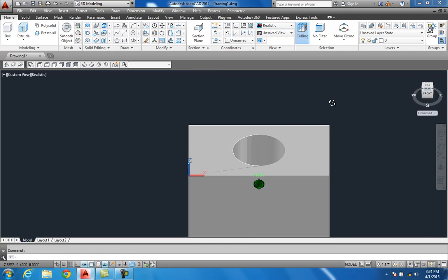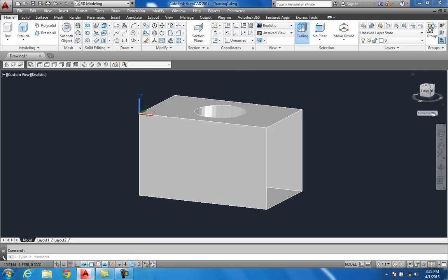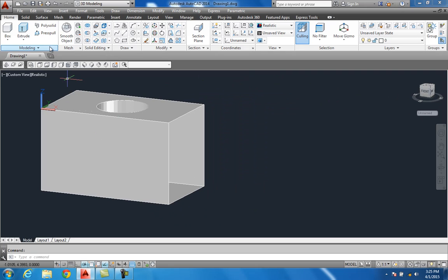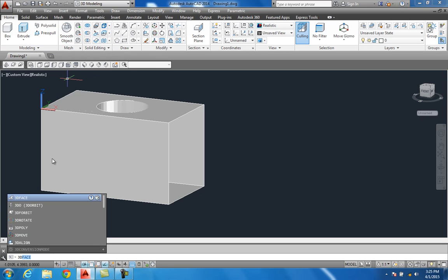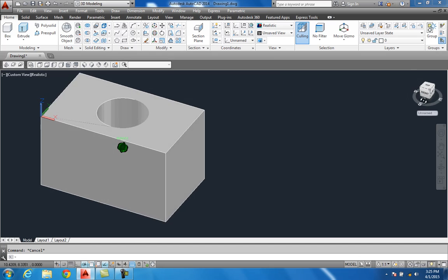And now you can see it's got that in, and all you'd have to do is just close your ends in by using a 3D face. Just catch those corners 4 times. Puts that on there. Rotate it around, or you can mirror that, whichever way is easier for you. And just that quick and that easy, you've got a 3D surface model. If you have any questions about this, and there's quite a few steps involved, just please contact me.